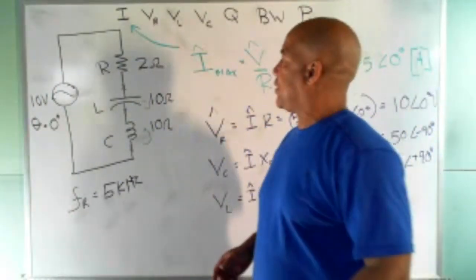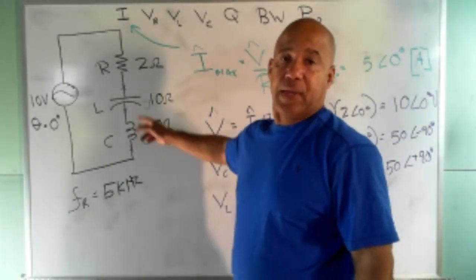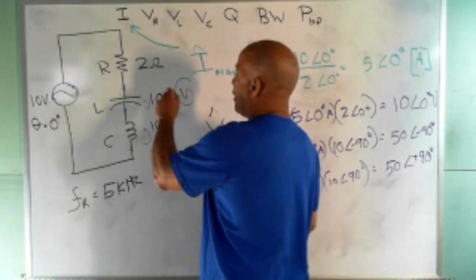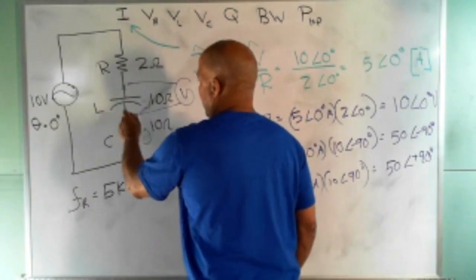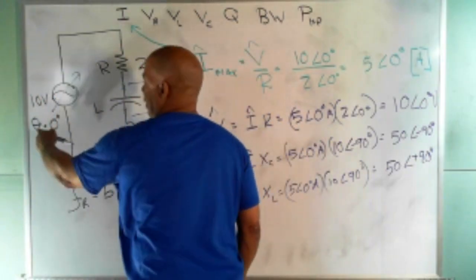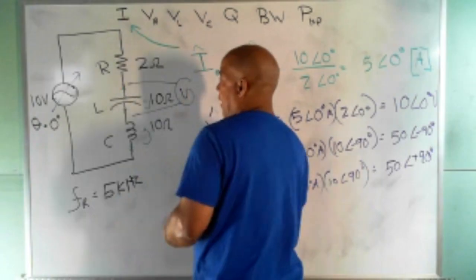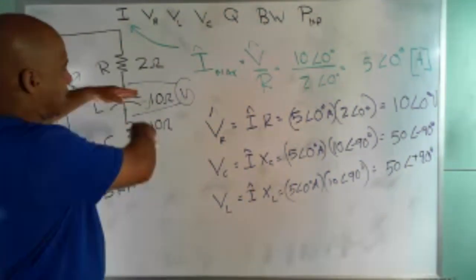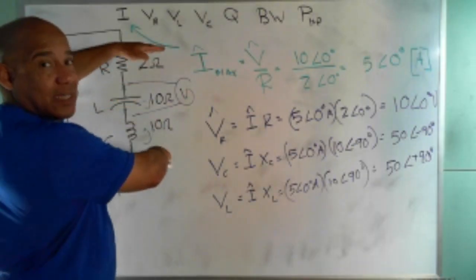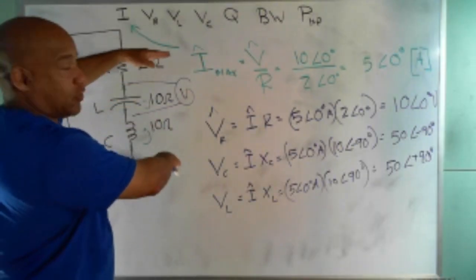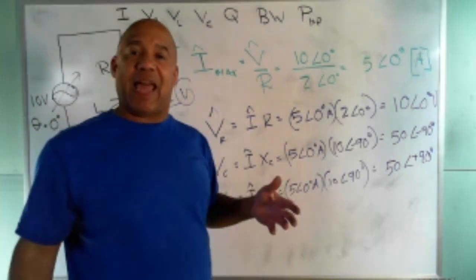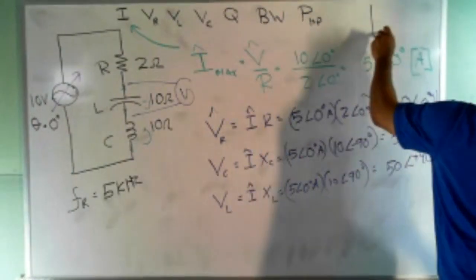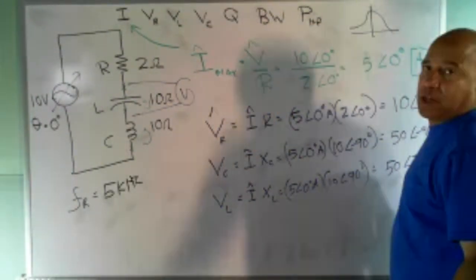If I had this circuit, I can take a voltmeter on AC and hook it to here. And say I vary the frequency. As I get closer and closer to resonance, what I'll see is the voltage amplitude will rise, and if I go past resonance, it'll start to shrink. So if we were actually doing this in the lab, you wouldn't see the resonant curve like this. This is the way we think about it, but you wouldn't see that curve on the oscilloscope.